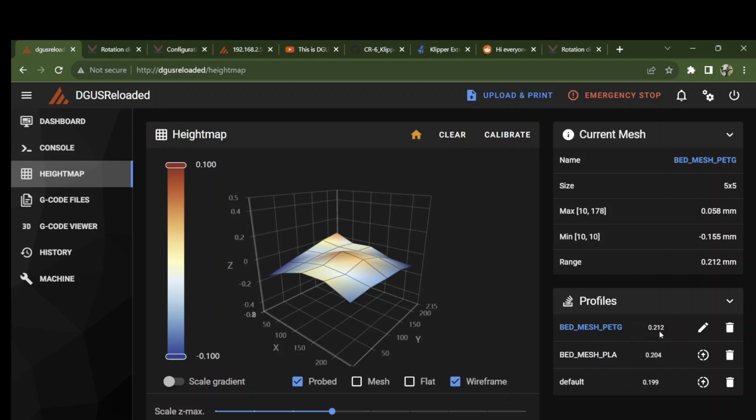You'll see the range of values that they've had. So see, minimum to maximum is displayable here just with rolling your cursor over the range values. You decide if a possible spread of one full layer height is good enough, or if you want to keep trying. You know, you engage in all that chicanery with silicon spacers and tightening things and running them again. People can spend days gleefully trying to perfect that. But quite honestly, your ABL can do that just fine as long as it is accurate. And it's not a big difference in total value between the PETG and default.